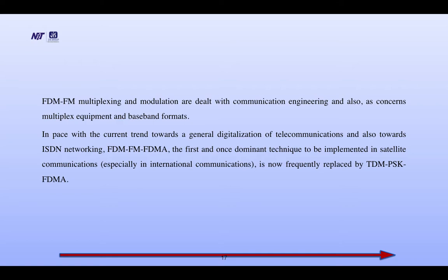FDM, FM multiplexing and modulation are dealt with in communication engineering, as are multiplexing equipment and baseband formats. In pace with the current trend towards a general digitization of telecommunication and also towards ISDN networking, FDM-FM FDMA, the first and once dominant technique implemented in satellite communication, especially in international communication, is now frequently replaced by TDM-PSK FDMA.